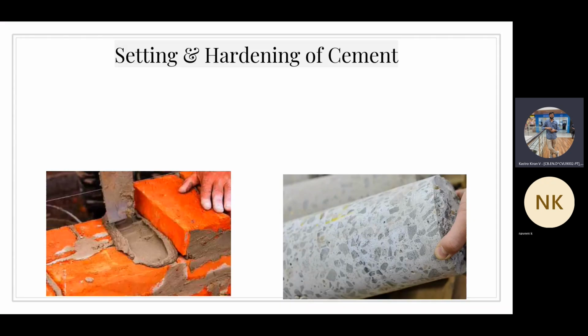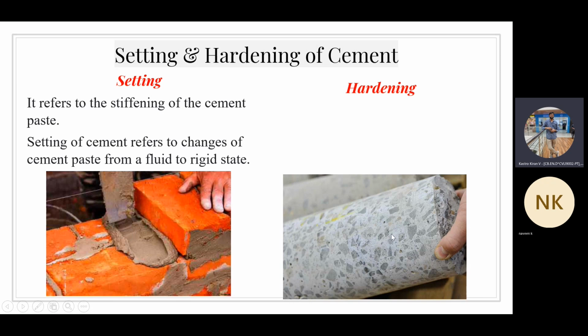So here, let's talk about the difference between what is setting and what is hardening. Setting is nothing but the cement paste will get stiffened. You can see here, the cement paste will be stiffer. It is not hardened. So hardening is nothing but the cement or the concrete will get hardened.